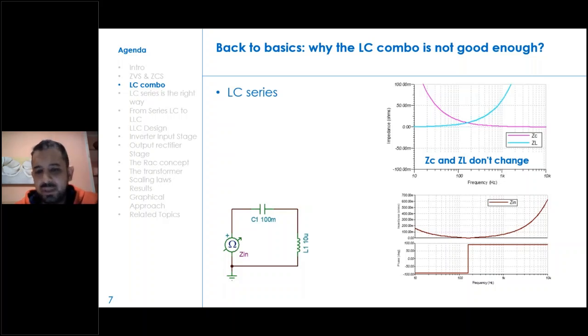So at this frequency they have the same voltage in amplitude, due to Ohm's law, but these voltages are 180 degrees out of phase. This is the reason why voltages on L and C in the series LC configuration tend to cancel.